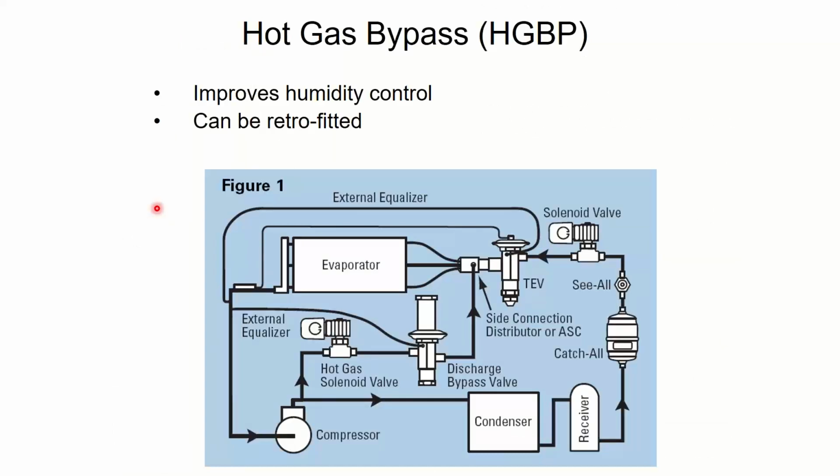We have a thing called hot gas bypass. Do not let your contractor talk you into this as being one of your stages. For one, the code doesn't recognize it as a stage. For 2, it's an energy waster.